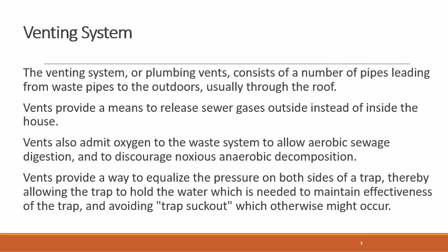Next is the venting system, or the plumbing vents, which usually consist of a number of pipes leading from waste pipes to the outdoors, usually through the roofs. So vents provide a means to release the sewer gases outside instead of inside the house.